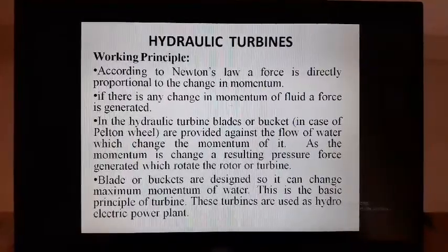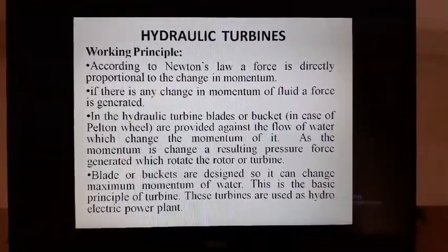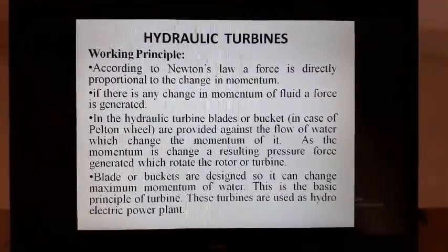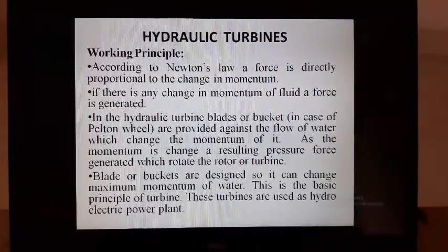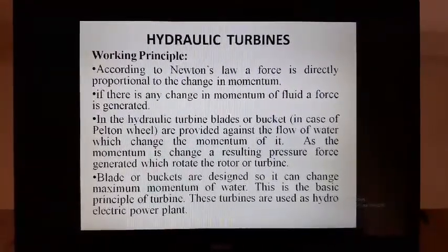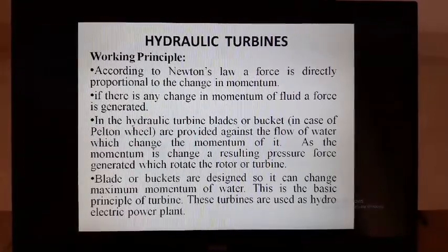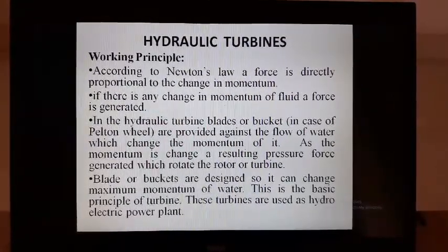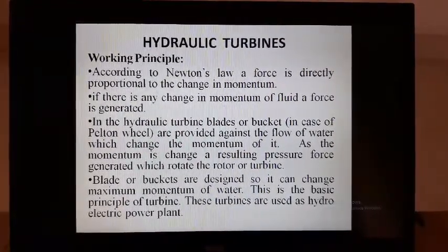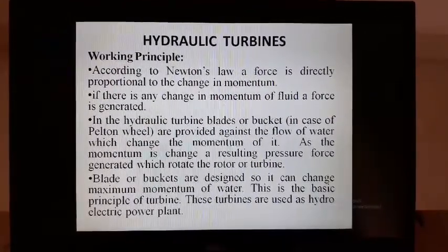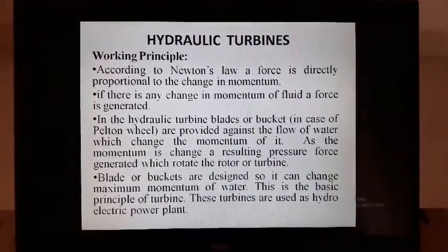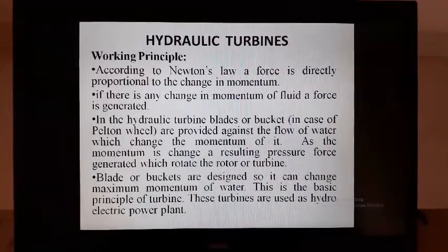The design of the blades or buckets of the turbine is such that we obtain maximum change of momentum of the flowing fluid or water. In hydraulic turbines, we use water as the working fluid. So, this is the basic working principle of the hydraulic turbine.